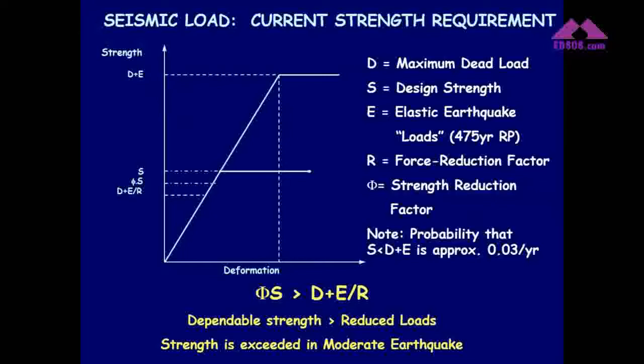The large earthquake loads act on our building, but we assign less strength to our members, and we want our structural members like columns to go beyond the elastic limit and to deform in the inelastic range. What I mean is to get damaged.